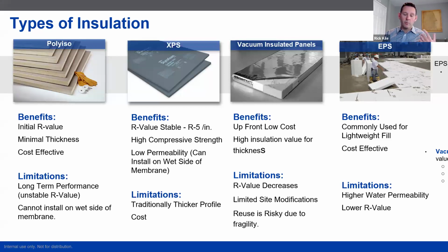So when we think about re-roofing and retrofit projects and an increase in R value from the time that the project was originally built to the time it's being re-roofed, we might have gone from 3-4 inches of insulation to 8 inches of insulation to meet our R value requirement. A vacuum insulated panel is a great way to keep that total assembly profile shallow and maybe eliminate the need to elevate building mechanicals or elevate roof parapets, which can have a significant cost associated with them as well.